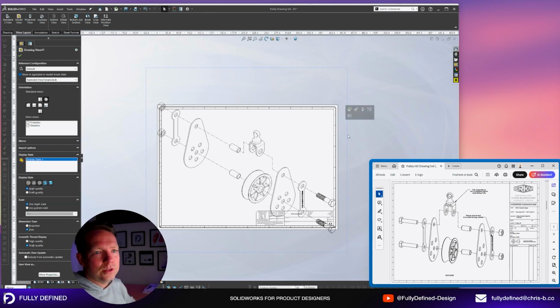All right, now this is your challenge. You have to get this into a 1:1 scale at an angle that's going to fit on the page. How would you go about it? First, I want to show you that you can create a custom view in your SolidWorks part or assembly file and then use that view in your drawing.